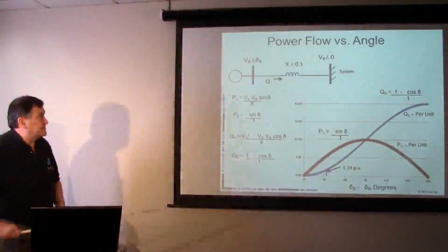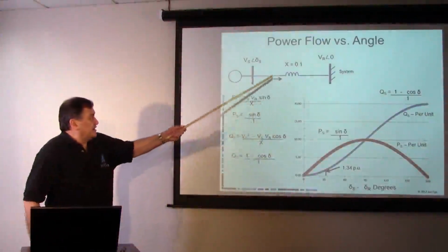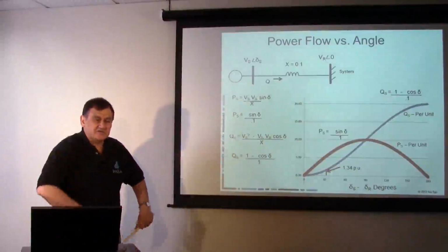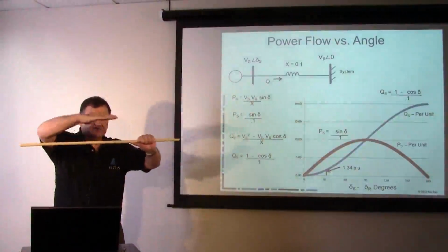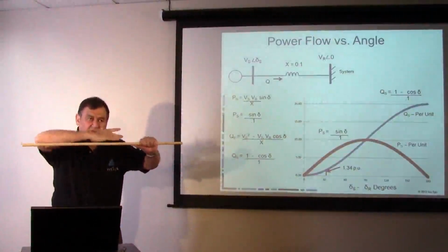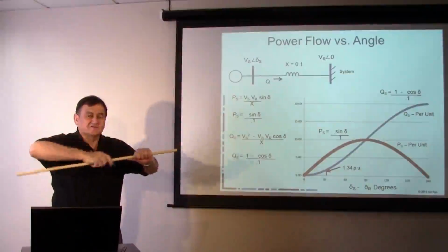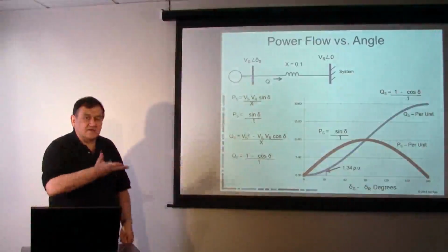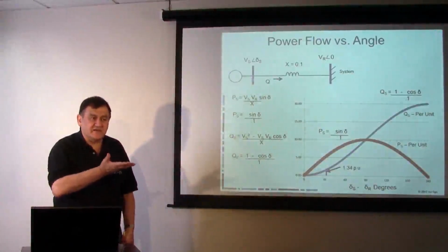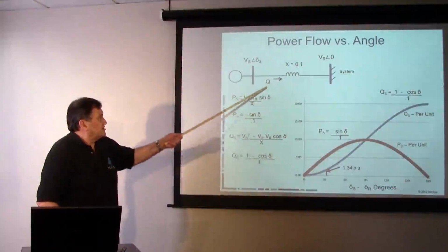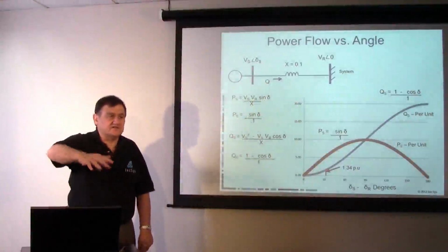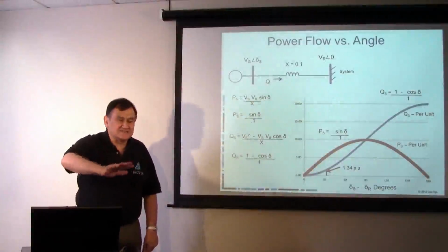This is a simplification. A transmission line actually has a capacitance because those conductors have a physical spacing. You can build up a charge on one conductor versus another. So based upon the voltage, you can get more and more megavars generated out of that line. So at light loads, it can be like a capacitor, but then at heavy loads, it turns into a very dominant inductive load. And you've got to really understand that.